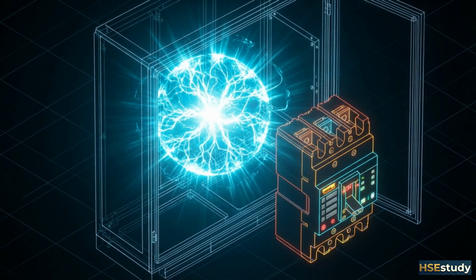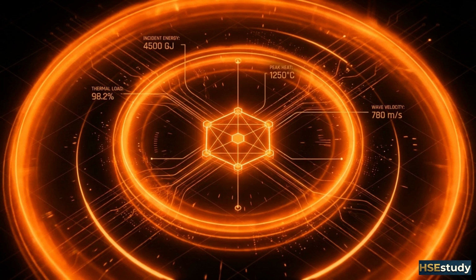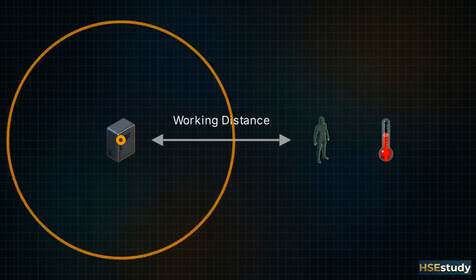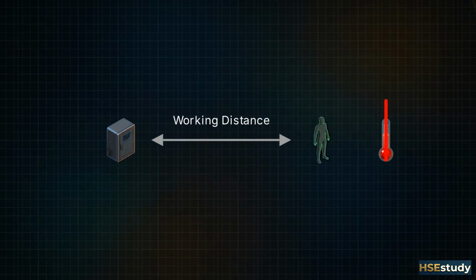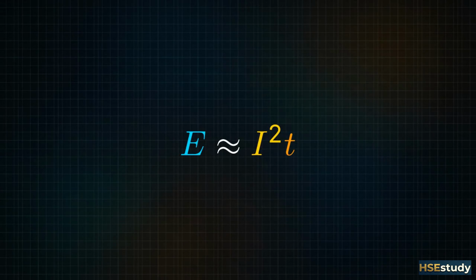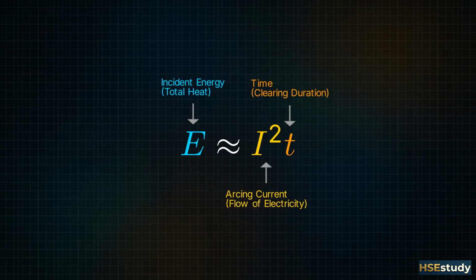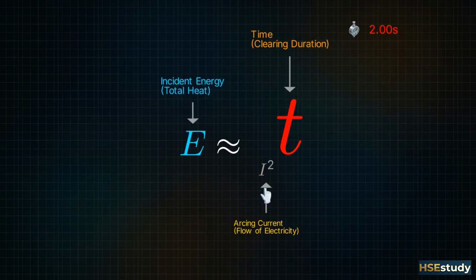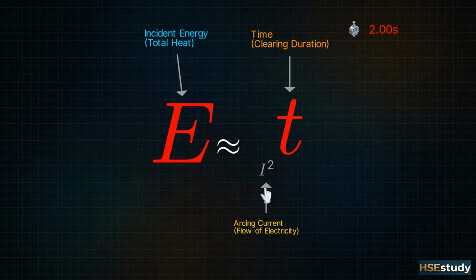An arcing fault pulls less current than a bolted fault, and this specific behavior creates a deadly blind spot for standard electrical safety equipment. To measure the danger of that blind spot, engineers calculate incident energy. Incident energy is thermal energy measured at a specific distance. Because arcing faults pull lower current, they often fail to trigger instantaneous breaker trips. This delayed reaction time causes duration to scale up, which massively inflates the total energy released during the event.